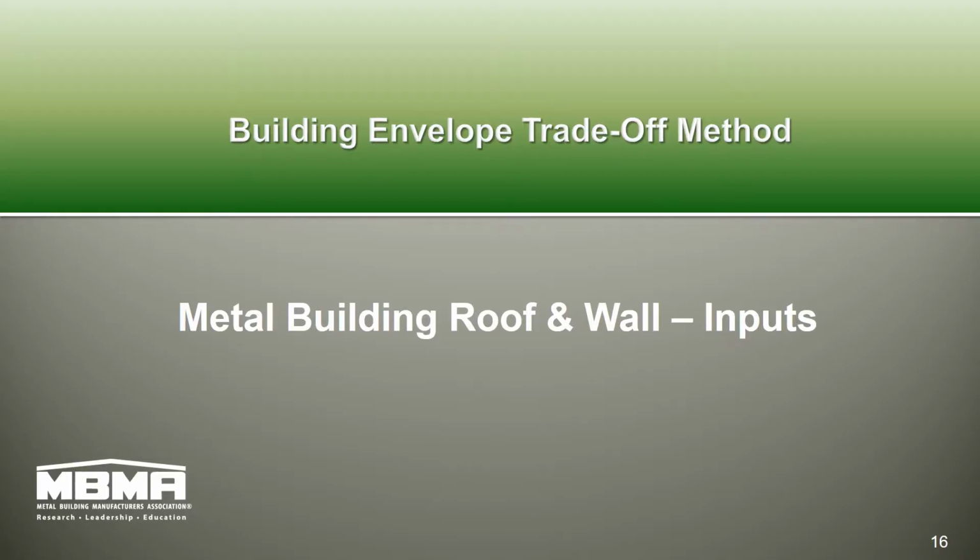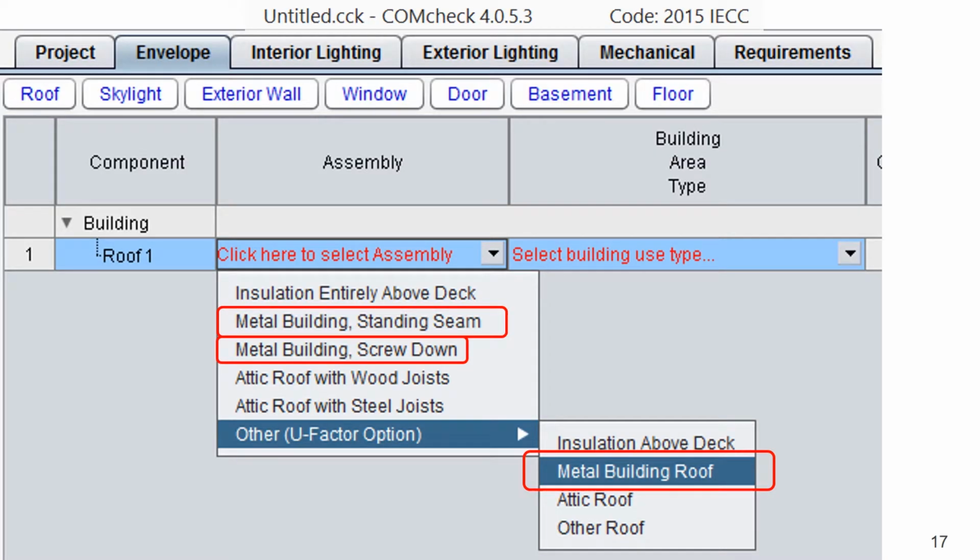So let's review the metal building roof and wall inputs. In the previous part of this webinar series, we provided a broad overview of CommCheck and how to navigate the project information page. This will get into inputting specific information into the building envelope page. When you select the envelope tab, you'll have 7 other options for entering in the roof information, the skylight, exterior wall, window, door, basement, and floor information.